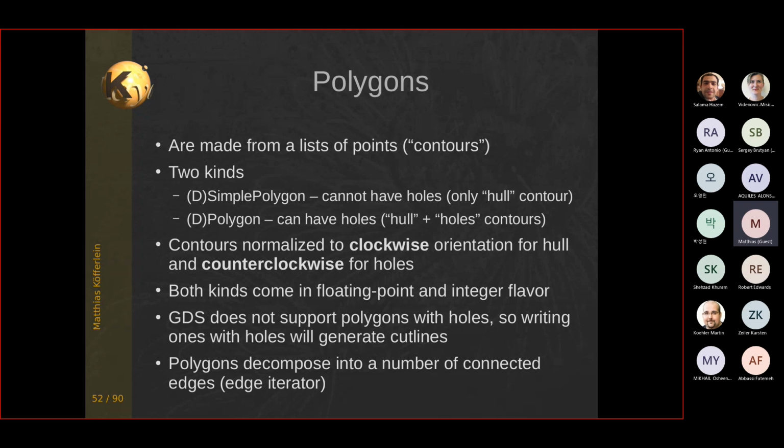But I know tools that have switches that allow you to configure the interpretation of those areas. And if your mask maker uses a different switch than you were using in your viewer, then you will see a layout which in reality is different. And that is really painful. And most foundries, if you send a chip layout to a big manufacturer, they often implement checks which make sure that you don't have such situations in your layout. So they forbid self-overlapping polygons specifically.